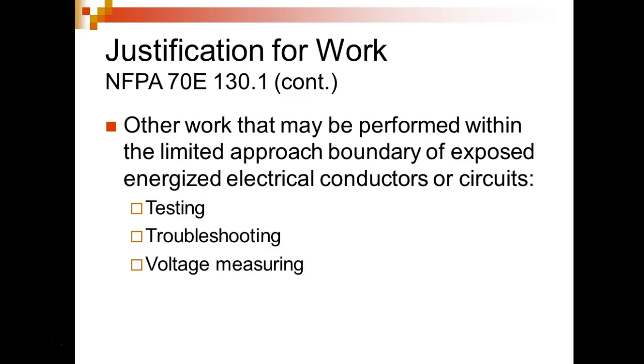We are the guys that can go past this boundary because we are responsible for testing, troubleshooting, and measuring those. But literally, that is the only time you should work on a live piece of equipment. You go in there, you take your tester, you make voltage measurements, you determine what's wrong, right? Then you kill power, you lock it out, you replace the part.